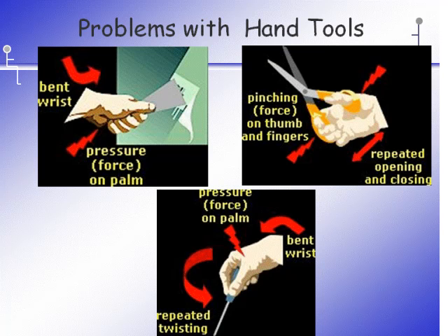Contact pressure, pressure from a hard surface, point or edge that is coming in contact with the hand. This can, of course, directly compress tendons, ligaments, or blood vessels because they run very close to the surface of the hand in the palm, as well as having the wrist in a bent or awkward position. So the best tool is one that fits the job that you're doing, fits the workspace that's available, reduces the amount of force which the worker has to exert, and also fits the hand.